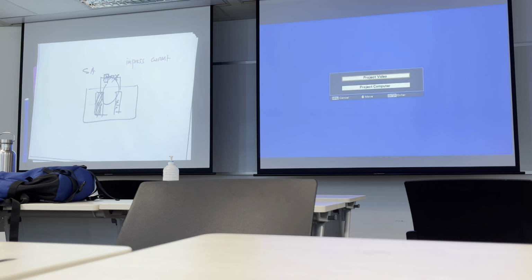If you provide the power source, that one will always be the cathode, so it will not corrode. If you do not turn on the power, you will have localized corrosion, where within the metal itself you have a cathode and an anode. This one, you force it to be the cathode.